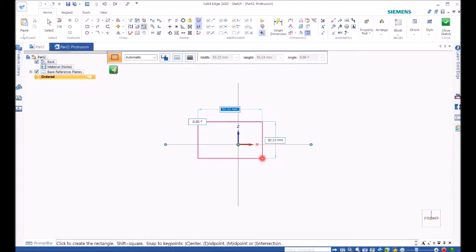And here you can see, as I move the mouse around, the dimension changes. In order to fix the dimension, you need to leave your mouse completely and type the figure on the keyboard, like 50. Okay, that changed because the mouse has been moved. So you have to carefully, without touching the mouse at all, type the figure and press Enter. Once Enter is typed, move to the next box.